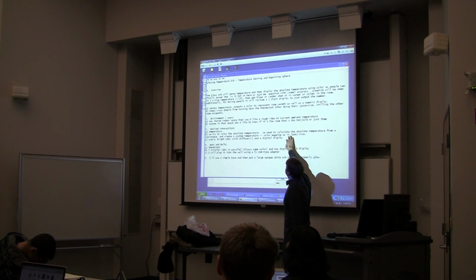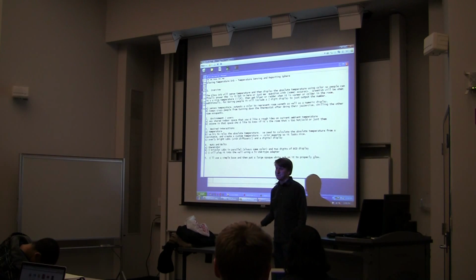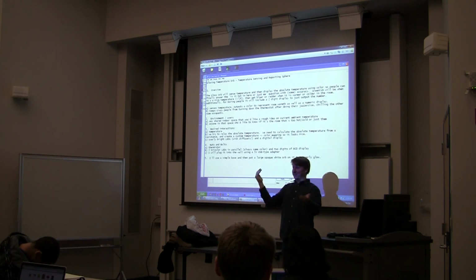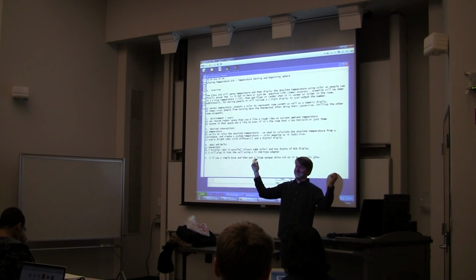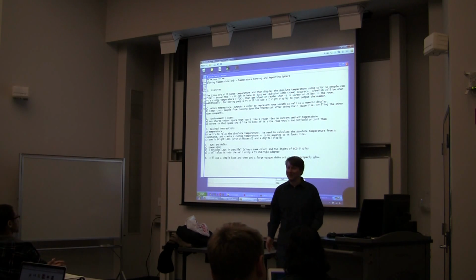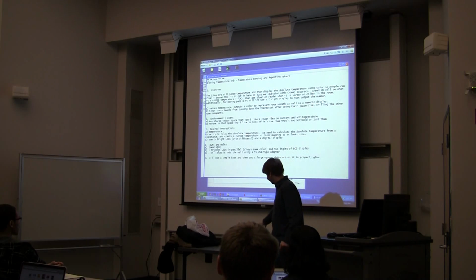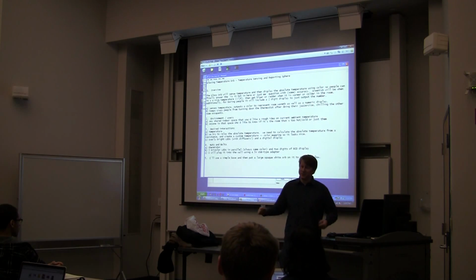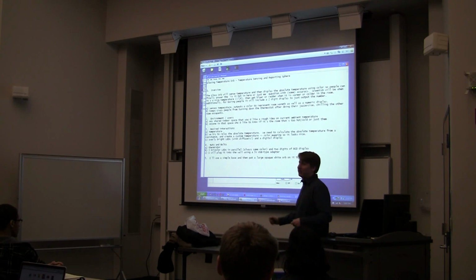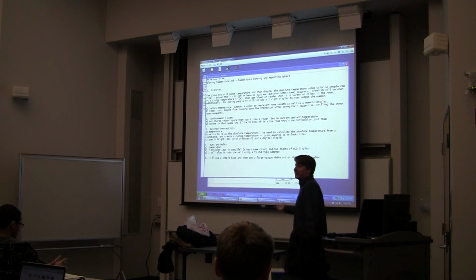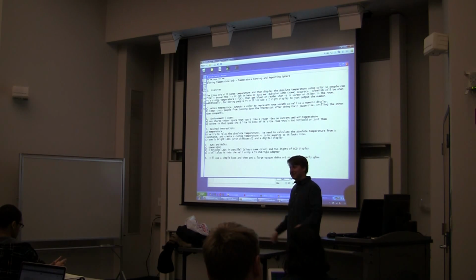And then we probably want to make some custom temperature mapping so that it looks nice, right? Because you can't just say, my thermistor gave me a value of 138, let me set my LED to 138. I don't know what that's going to do. It's probably going to be something crazy. So, if you think about it, you can play with the colors. Maybe you go look up those color temperature charts on websites and just get a feel, and you say, well, blue is going to be cold, green will be some happy temperature like 72 degrees, and red is going to be something over 80 degrees. You kind of just work from there.